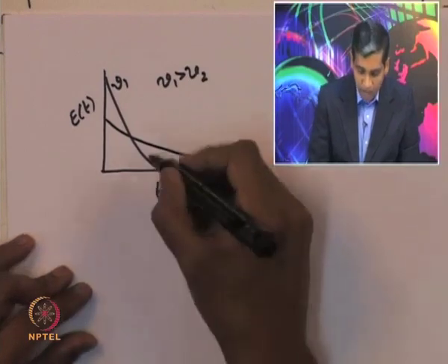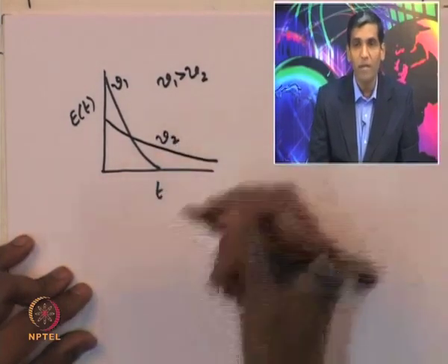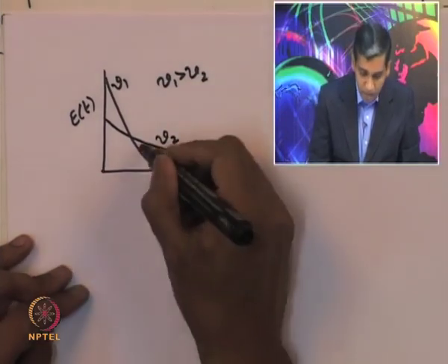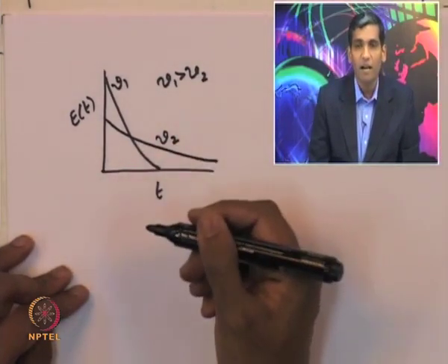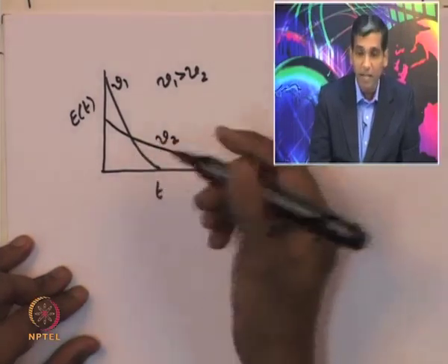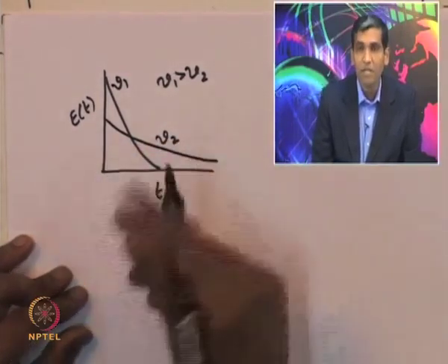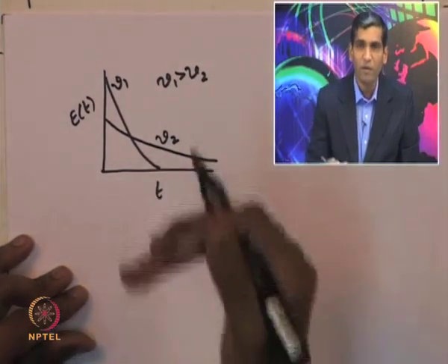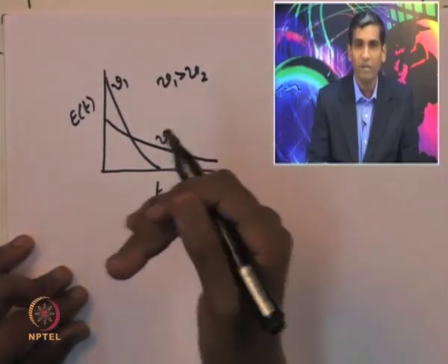So, now because of this problem, this corresponds to volumetric flow rate V 2, and because of this issue it is very difficult to now compare the E curves at different conditions, because the E curve is now going to be dependent on the volume of the reactor and also on the volumetric flow rate with which the fluid is actually being fed into the reactor.